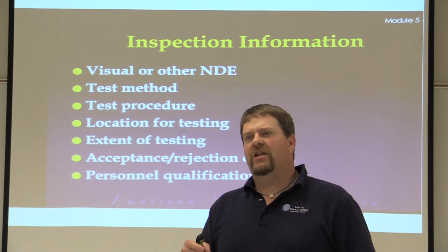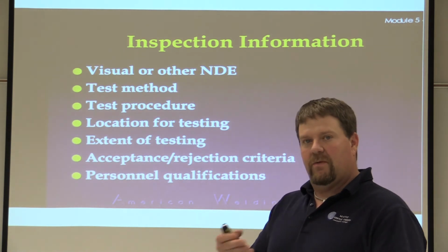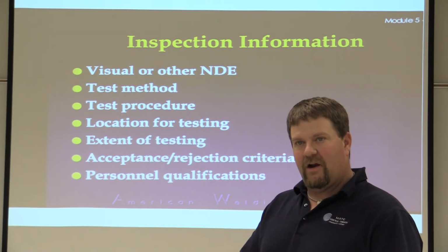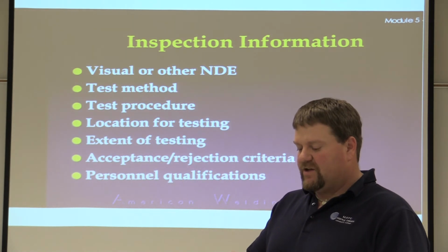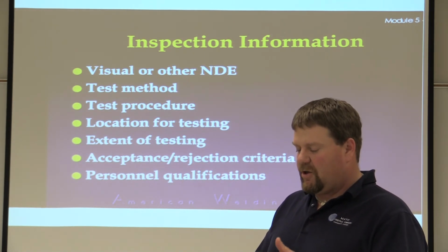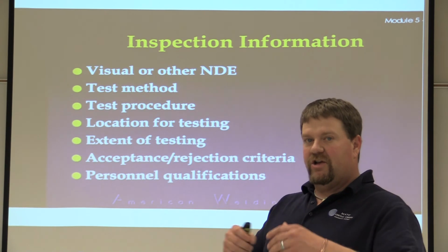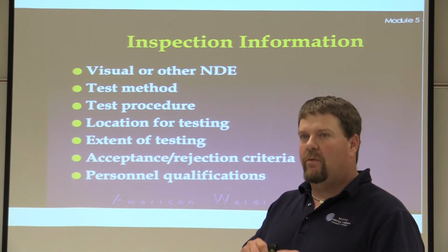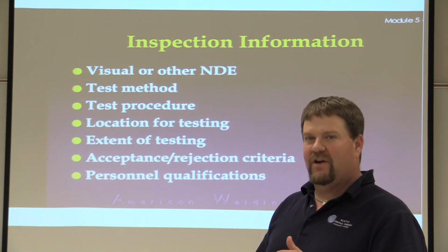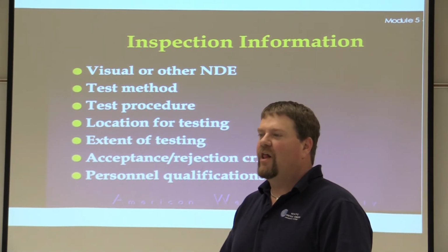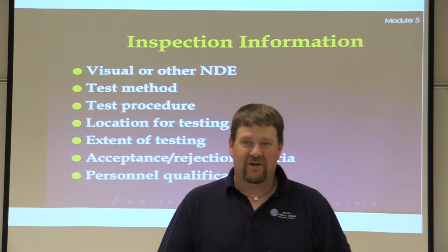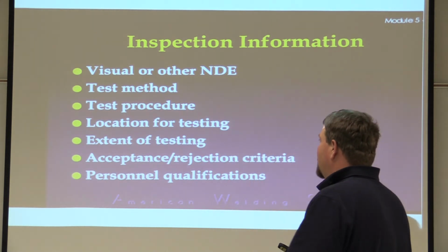And sometimes, a lot of times, the inspector is just looking through the paperwork of the fabricators, the documentation for the codes and the certifications. I can see a name, I see GTAW, and you'll just flip through it. Unless you take a fine-tooth comb and look at it and say, oh, it's for ER70S-6, which is steel, versus 308L or 309L, they're going to try to sneak you in on that job, okay? So you got to be careful about it.